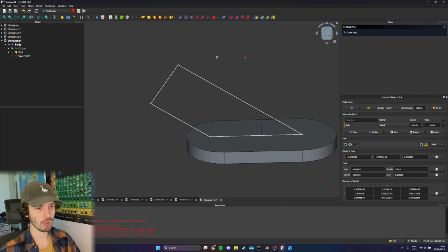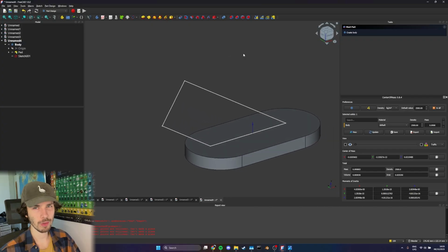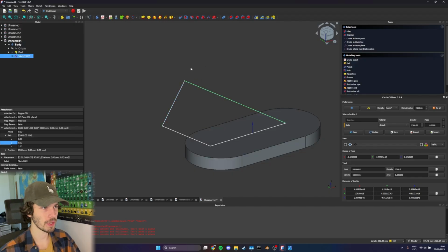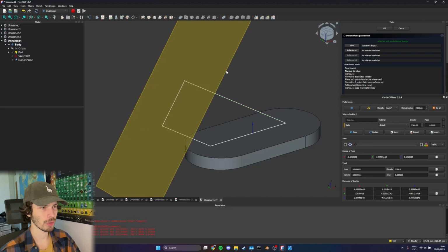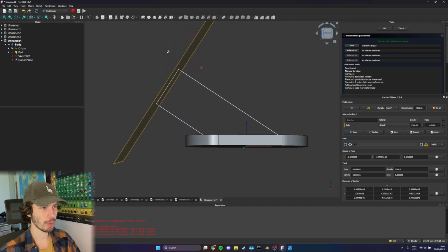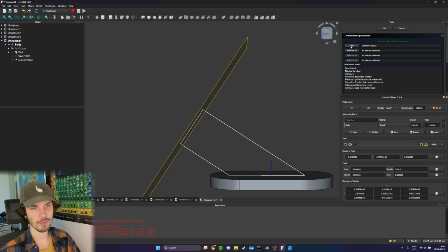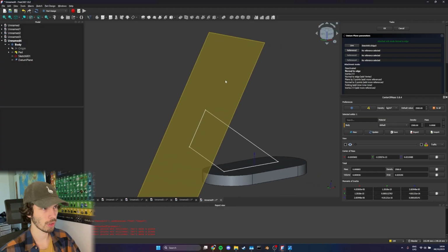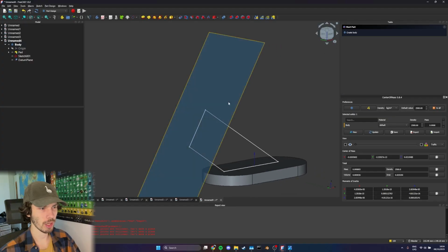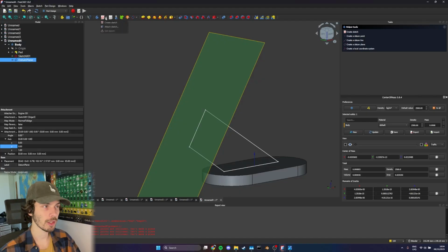Even though we have the whole geometry over here for the pipe, we'll be creating a datum plane to create an extruded pipe. For that, we'll be selecting the top longest piece, and over here, hovering over datum plane, create a mesh. If it doesn't show you perpendicularly to that edge, find the edge underlined reference over here, click around, you'll figure it out. Once that's good, let's press OK, and we have our datum plane. On that, we create a sketch.